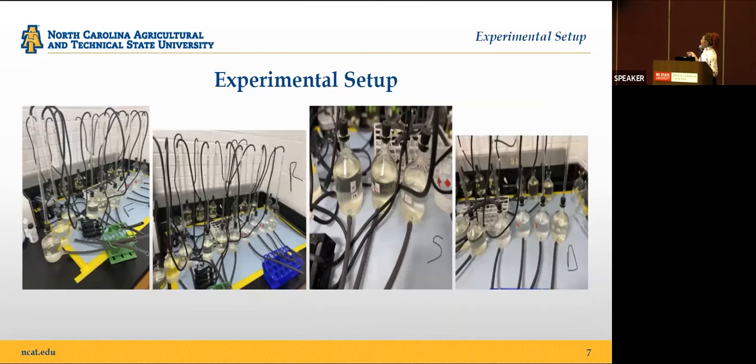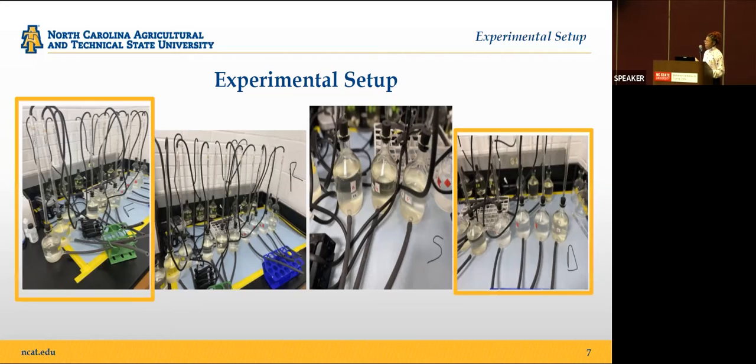So this is our experimental setup. We use glass bottles with the ability to withdraw water from them. We also have rubber stoppers that have pipettes in them with tubes connected to our air pump so that we are able to aerate our experiment. And these stages, like I mentioned twice before, are where we sample our water. So in this first stage, the filling stage, the water has yet to be treated. And in this second sampling stage, the drawing stage, we should have our treated wastewater.